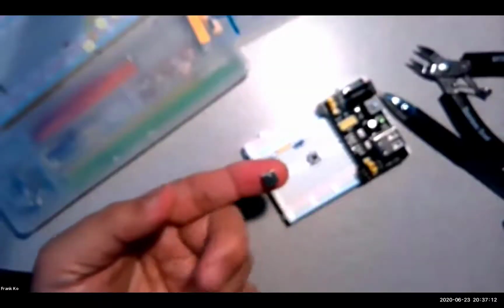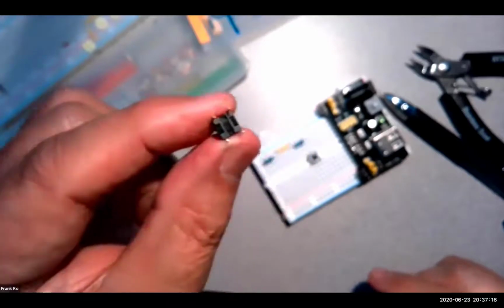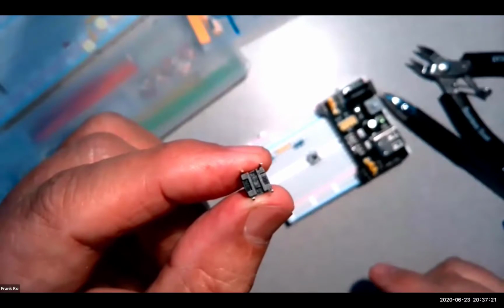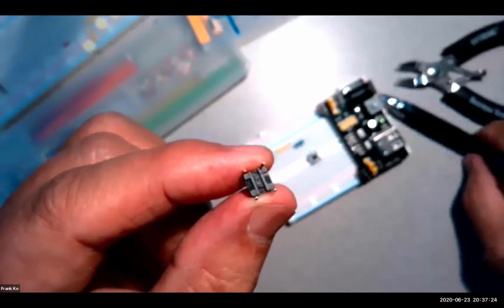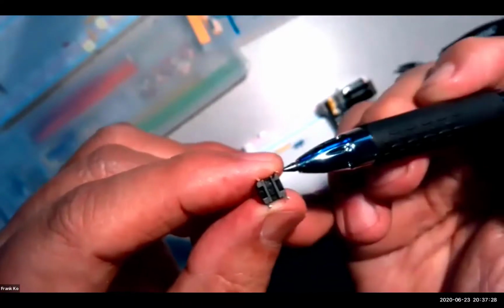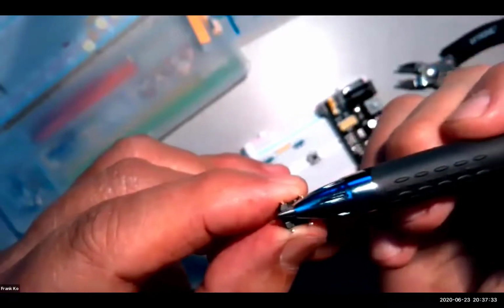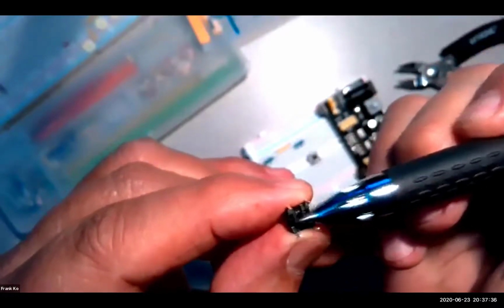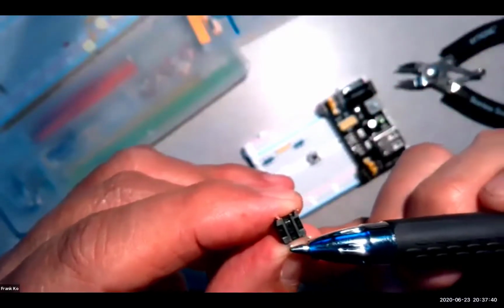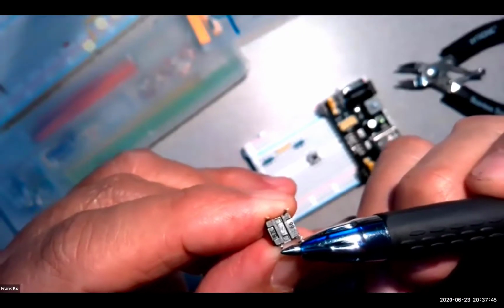Yes, okay. Yeah, the little switch, if you look at the back side of the switch, you'll notice that the spacing between these tines, these pins, are not equidistant. You have a pair closer to each other, a pair closer to each other, but this pair and this pair are farther apart. So the groove sits between right here. So this pair that's closer together is on one side of your dip support groove. This pair of pins that's closer together sits on the other side of your dip support groove. And that's how it goes onto the board.